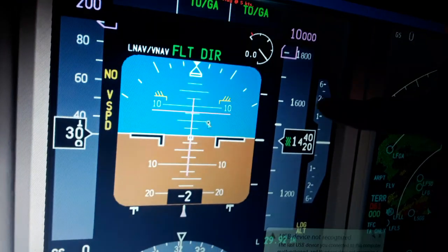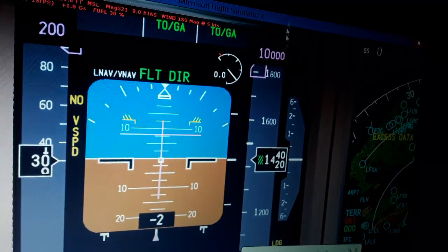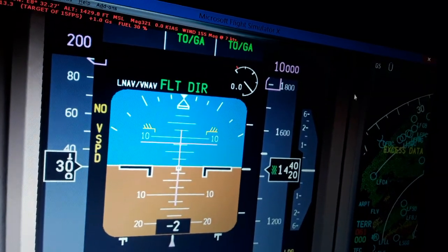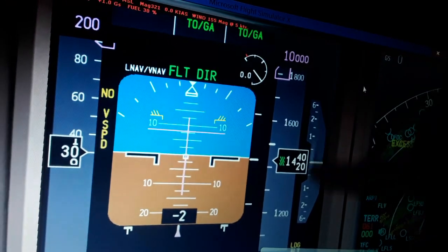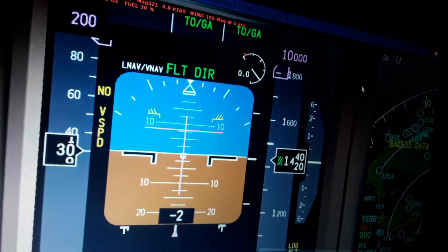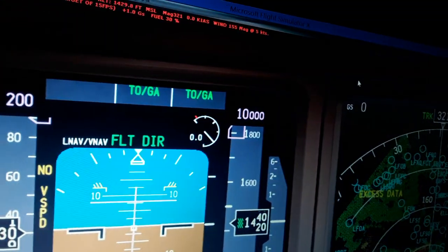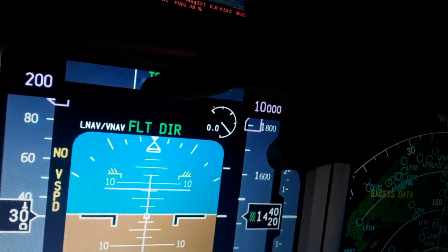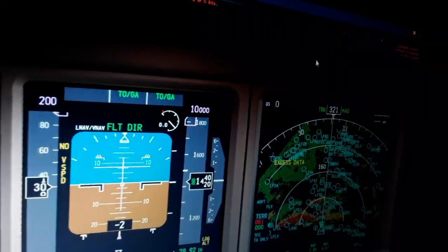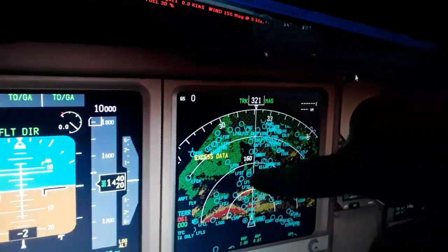That is very important also. Over here we have the rate of climb and descent of the aircraft in tens or hundreds or thousands of feet, over here on the right, just beside the barometric altitude. So you can see the modes, the flight mode annunciator with the auto throttle and the autopilot modes. We have the navigation display here.